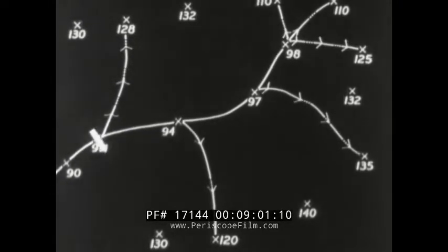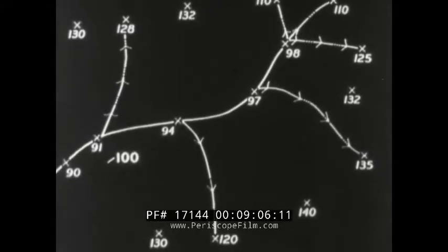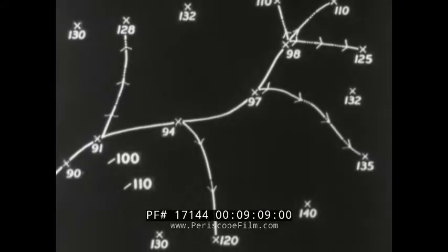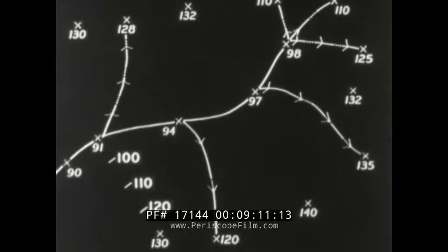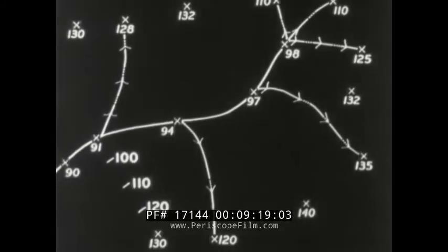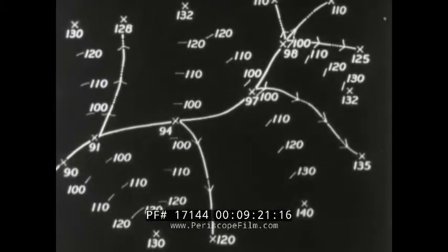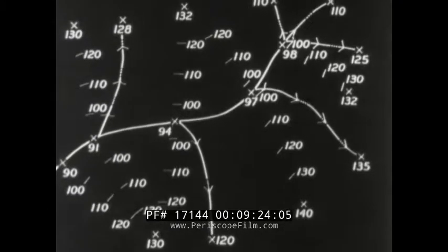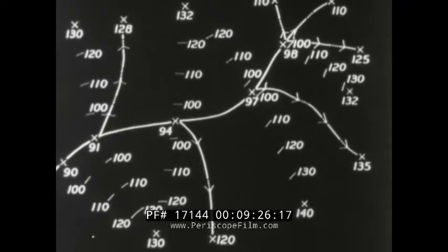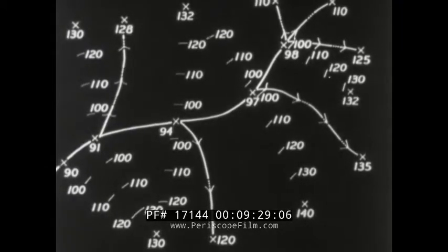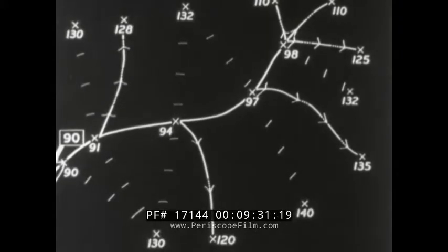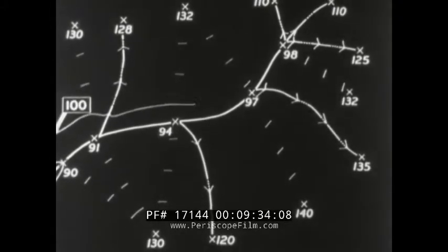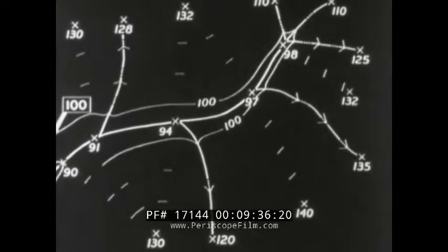Next, on a ridge line between 91 and 130, interpolate 100, 110, and 120. Since these points are where contours round the ridges, indicate them lightly by dashes. Continue this process until such interpolations have been made along each ridge. The elevations of these points should be multiples of 10. Finally, sketch in the contours, joining the corresponding V's and dashes.